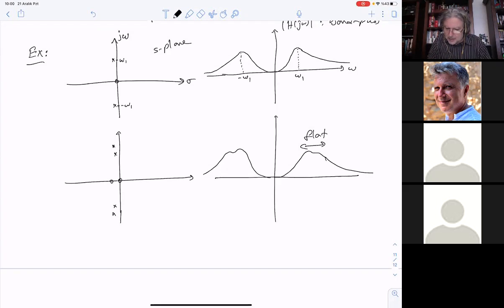And this point, by the way, is also a little bit more flat as opposed to the previous one. The previous one was like this, but now it is like this, a little bit more flat, because of these two zeros here. I could put more poles and more zeros, like another 0 and 0 here, and another pole here and here. That would still be a relatively good bandpass filter. It's going to be even flatter around this range.